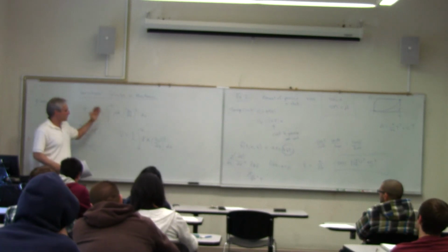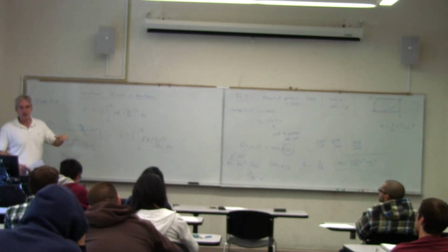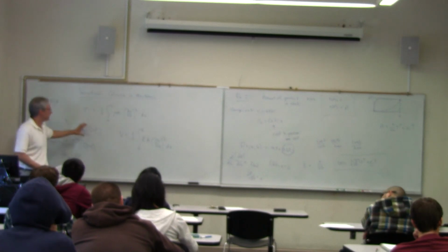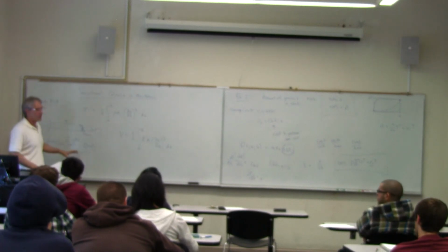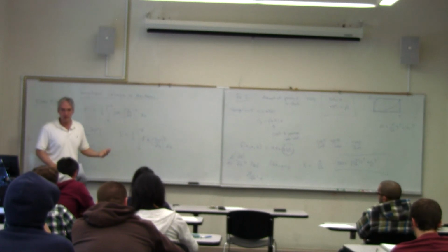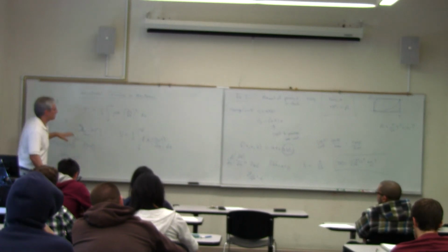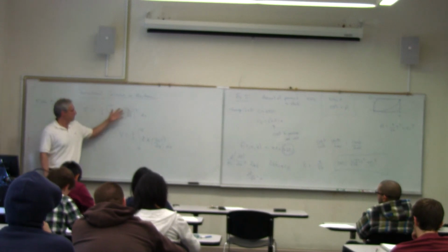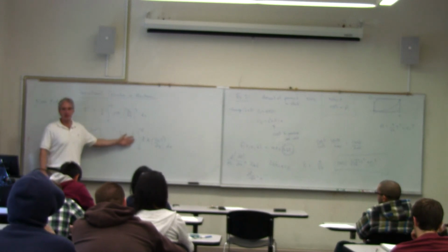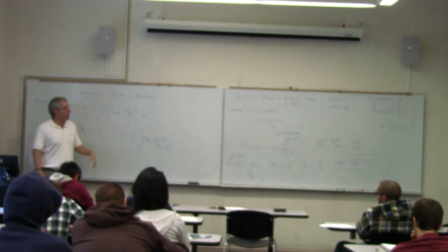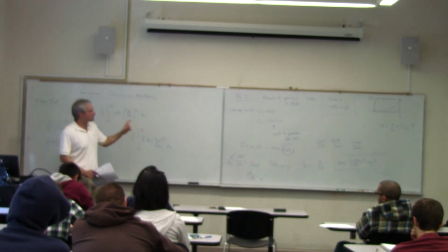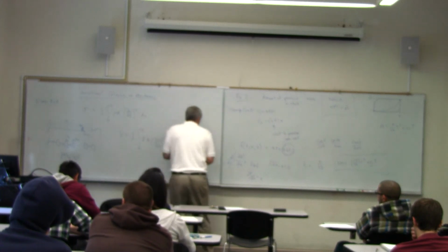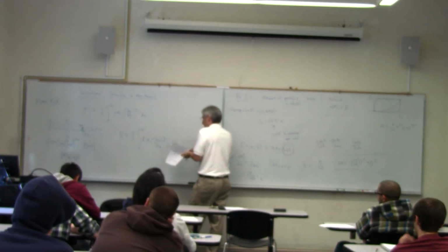This will not give you a system of ordinary differential equations. The equations of motion for a continuous system like this will be partial differential equations. So you cannot use Lagrange's equations to get equations of motion from potential and kinetic energies that look like this. However, we can still use variational calculus to get an answer.